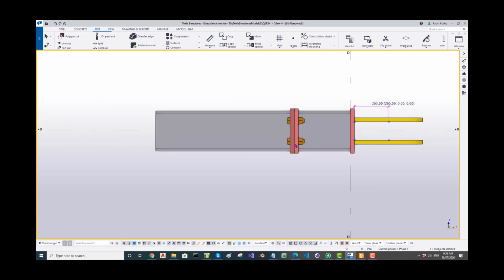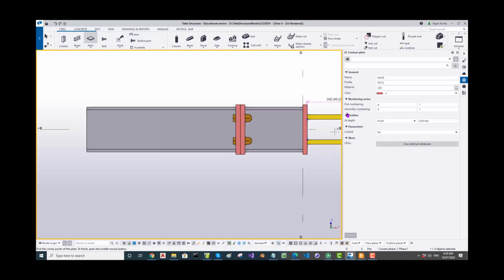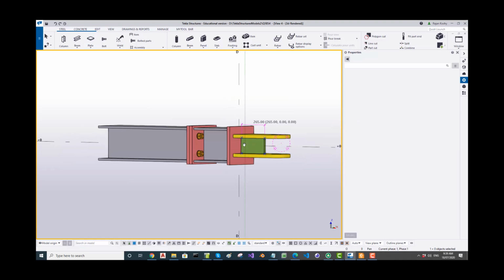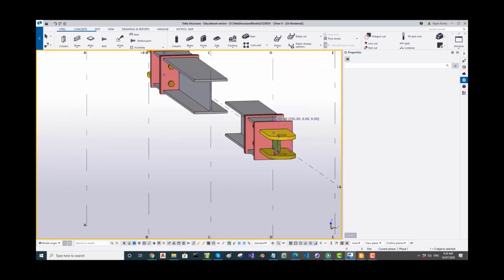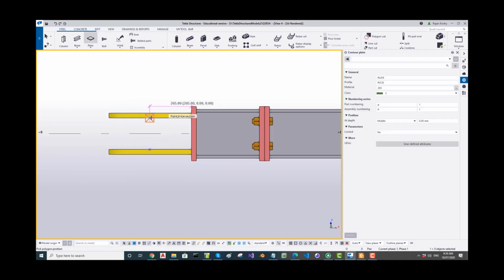This time it's going to be 20 thick, and it is not going to be forward or backward, it is going to be in the middle. So go to steel, plus press shift key and plate, and at depth, not in the front, in the middle. Okay, and what is the thickness is going to be 20. Let me change the color to 3. Okay, and now I am going to go that one, that one, that one, that one, and middle button. Check whether it's come all right. Yeah, it looks like all right. Okay, and here also plate, here, here, here, here, and here.